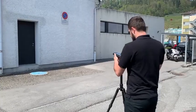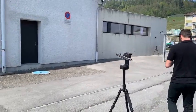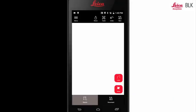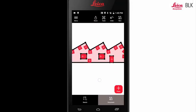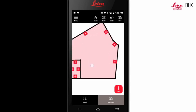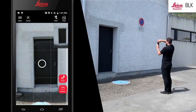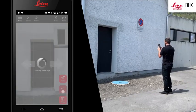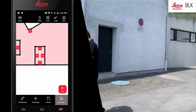To do this, take the BLK3D from the DST360 adapter and approach the wall you want to capture. On the display, select the Document tab and then select the plus icon of where you want to add an image to. If the icon is not in the spot you would like, you can create a new one or move an existing one. Step to your object and capture it. The image will be automatically saved to your selected place icon.